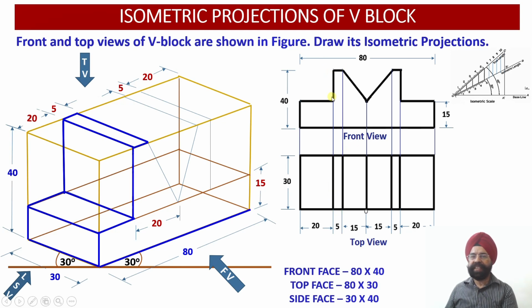Then we had discussed that this is a vertical wall. So this vertical wall has the dimensions, how much? 25 millimeter is the height and 30 millimeter is the width over here. So please check, 30 millimeter is the width of this vertical wall and 25 millimeter is the height of this vertical wall. So all the four elements of this vertical wall have been identified. Then there is this surface, which is a flat surface having a thickness of 15 millimeter, and the width is equal to 20 millimeter. So this is the width of this segment of the V block.